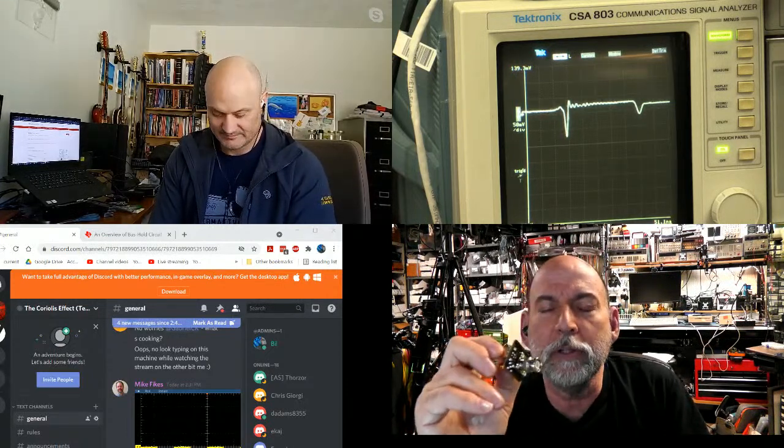I took it to mean that I knew what I was really looking at, instead of just accepting whatever the pulse was. The reason I looked this up and ended up on the CSA 803 is I wanted to show the effects of vias and square corners on a trace, because everybody goes, oh, don't use square corners.